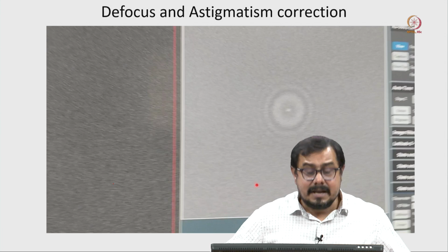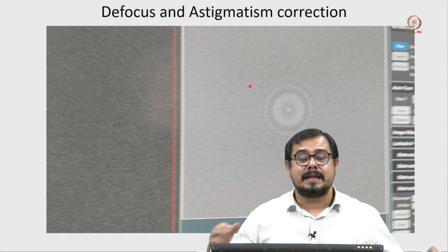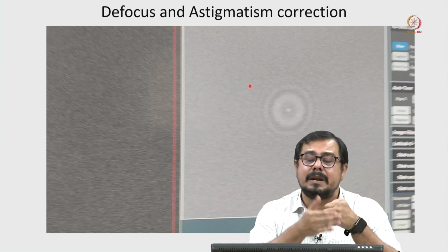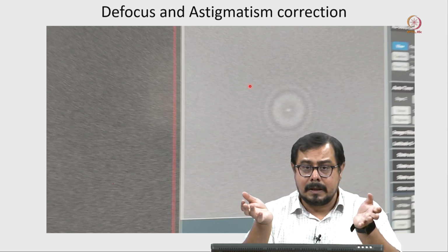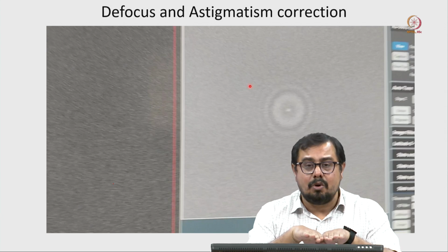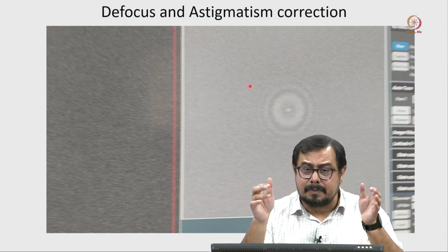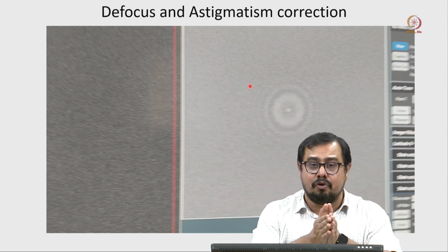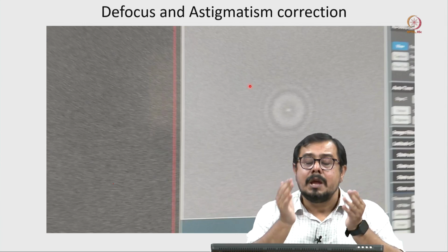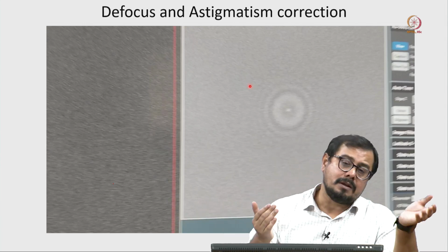Now I am coming to the next point, which is very important: what kind of fringe we can see when we have different defocus values. I told you that at zero defocus value you cannot see your image clearly. Zero defocus means it is actual focus, but at actual focus our eye cannot see it clearly, because there will be no white fringe or black fringe.